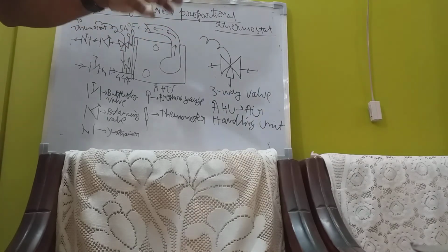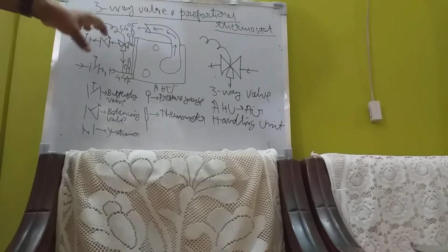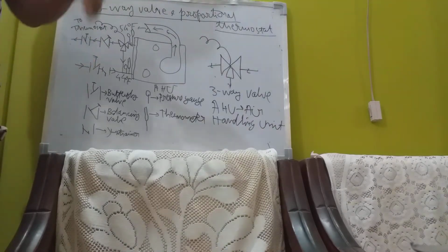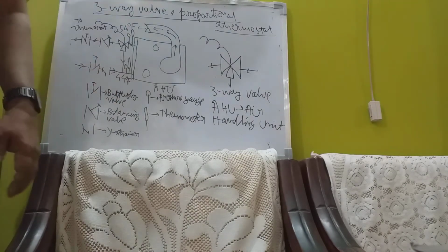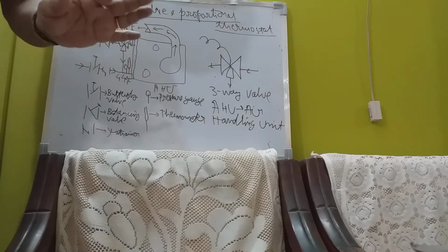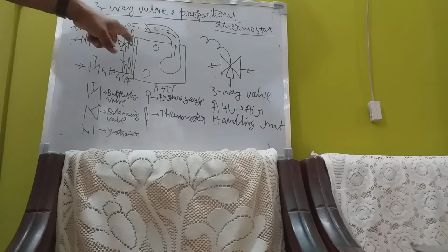What I mean to say is, in case of Sundays, I am talking about when the people load is more. But in case of working days, when the people load is very less, or sometimes in the working days, even during evening, the people load increases to some extent. During noon time, there is very little people load in the shopping mall. Generally, I am telling the general trend. So in that case, in the noon time, you need less chilled water flow.